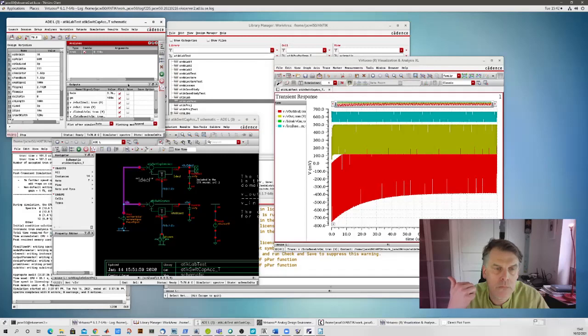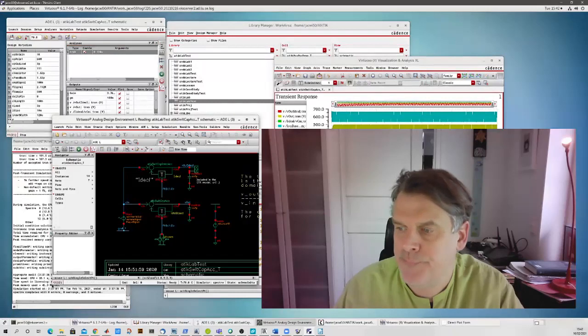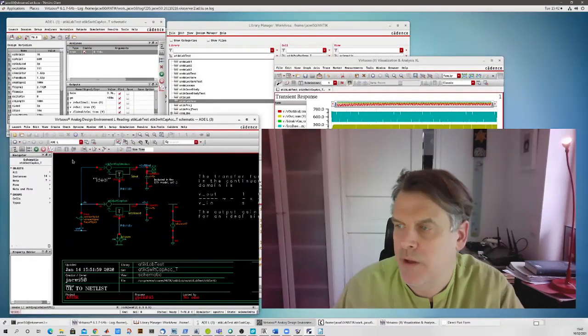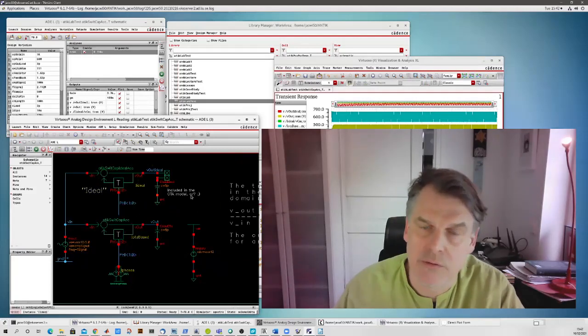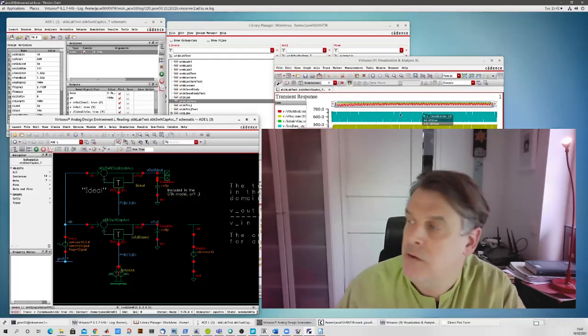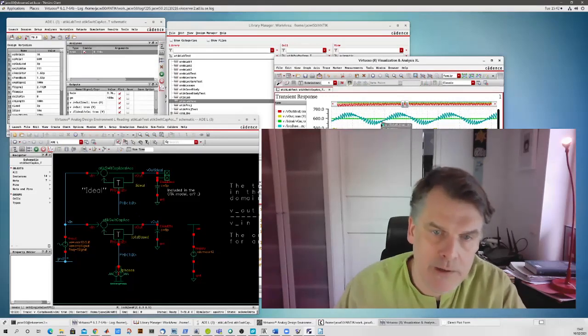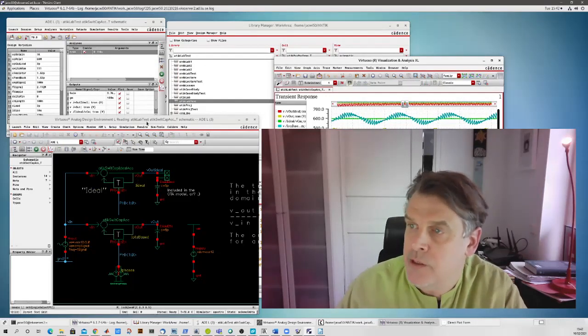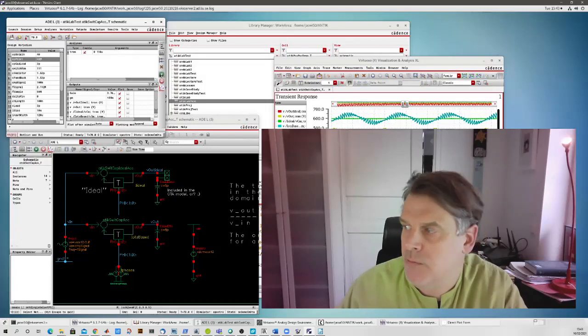So I think the key message with this lab is to understand these particular things. If we compare the ideal with the non-ideal one, take a walk through the different nodes and voltages and compare them with each other, and see how your design differs from the ideal one, and perhaps understand why. So for example, could gain be the issue? We know our circuit has a really poor gain, so let's try to change the ideal op amp to 40 and run a simulation.